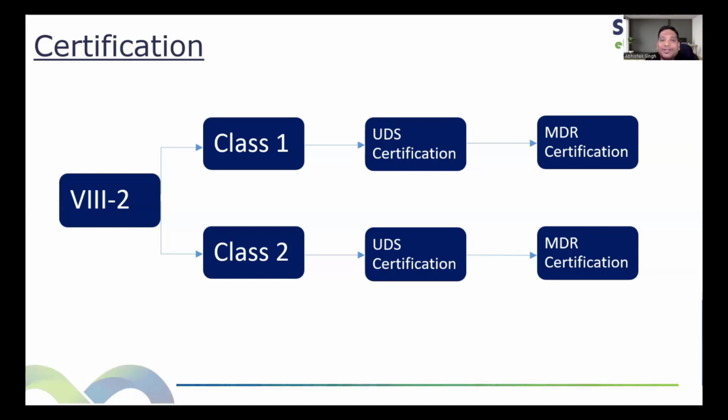When do you need to certify the MDR for class 1? When there is fatigue, or you are following Part 5. Some calculations were not available, the design by rule was not available and you had to perform FEA. In that case, if FEA calculations or fatigue calculation are included, then the MDR needs to be certified by a professional engineer for class 1.